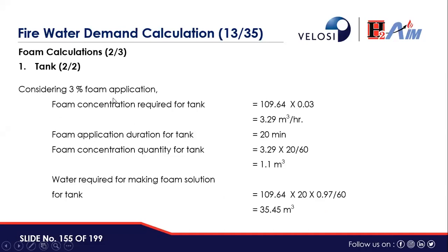So considering 3% foam application, we are multiplying it with 0.03, and with the duration of 20 minutes, the foam concentrate quantity of our tank will be 1.1 cubic meter. Water required for making foam solution for the tank will be 35.45 cubic meter.